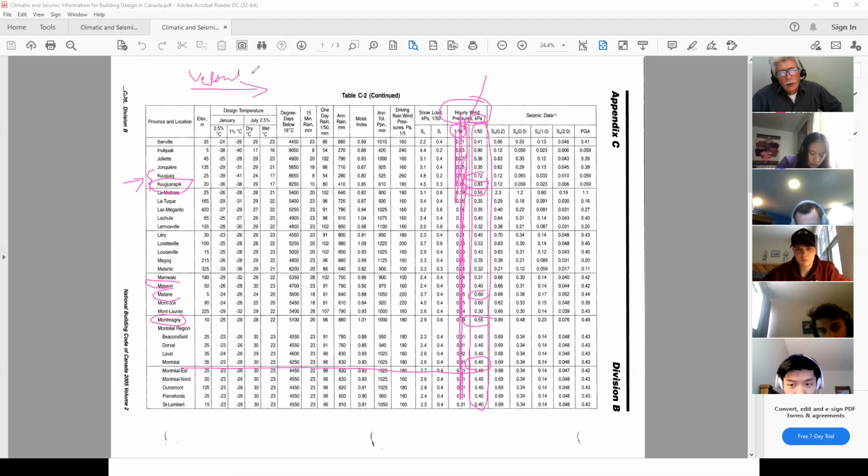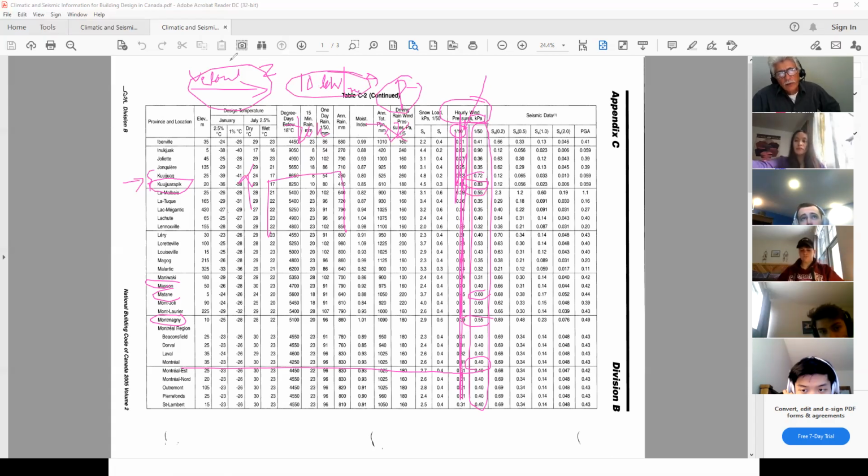Now, guys, I want you to appreciate this: wind pressures increase with the square of the velocity. That means that if I have a wind blowing at 10 kilometers per hour, it's going to give me one pressure. If I have a wind blowing at 20 kilometers per hour, it's not going to be twice as strong, it's going to be 4 times as strong. In other words, it goes up by the square of the velocity of the wind.